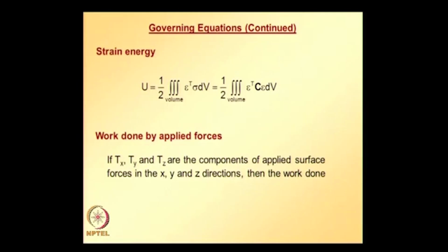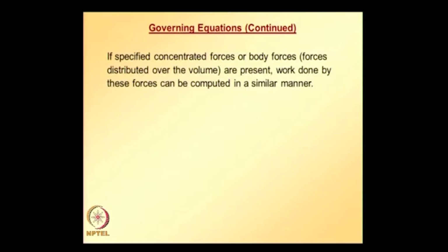Now, work done by the applied forces. Work done by the applied forces is given by components of traction along x, y, z directions multiplied by the corresponding displacements and evaluated over the surface over which traction components are applied. So, work done by the applied forces is given by this surface integral, and if concentrated forces or body forces are present, work done by these forces can be calculated in a similar manner.